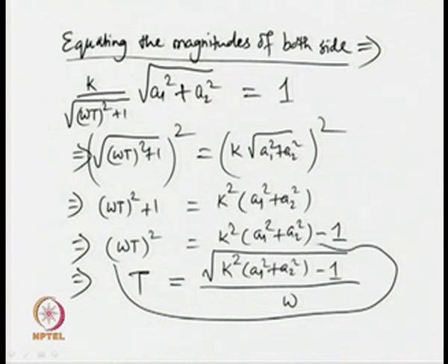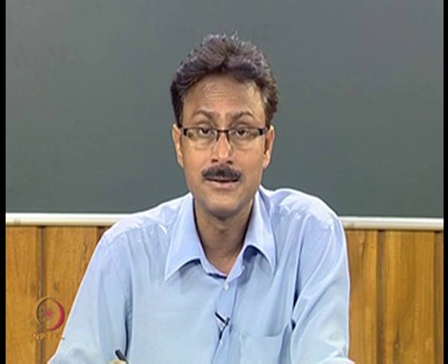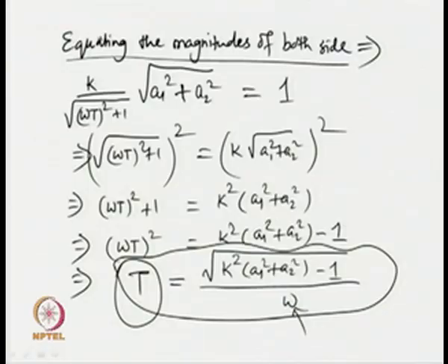So, the beauty of doing this describing function based analysis is that we have been able to get an explicit expression for one unknown associated with the transfer function model in terms of the measurements. What is the measurement? That is ω, and there are also measured values used in A1 and A2. Okay.